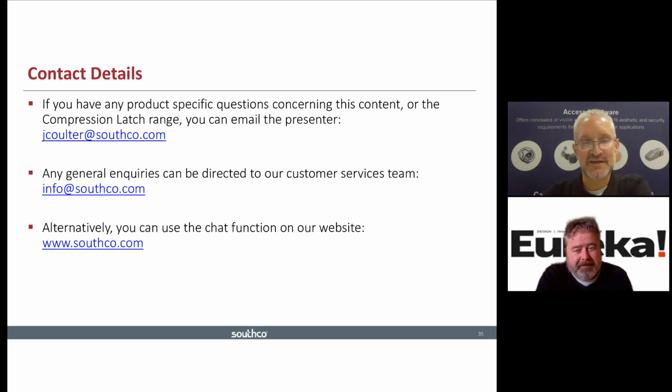Very good question. As you know, some of the latches I discussed earlier are a lever and handle together. So when the latch is open, the handle pops up, and it's very easy to see from a distance or close up that your latch is not secure. But there are other latches, like some of the self-adjusting latches, which are smaller, or the quarter turn latches, where all you see is a head sticking out of your application. And it's very hard to tell from a distance whether it's been rotated shut or rotated open.